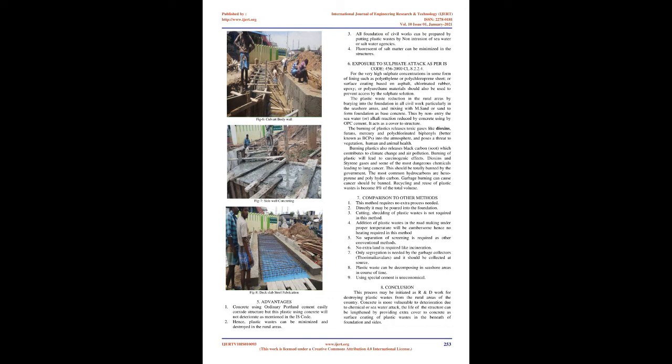By using plastic waste as modifier, we can reduce the quantity of cement and sand by their weight, hence decreasing the overall cost of construction. At 5% optimum modifier content, the strength of modified concrete was found to be several times greater than plain cement concrete. Using plastic poisons our food chain and affects human health. Disposable plastics are the main source of plastic. Plastic pollution is not only in the ocean but also in the desert.